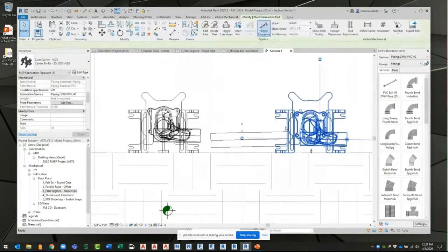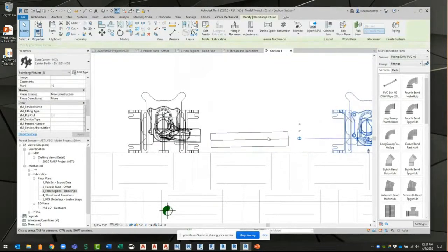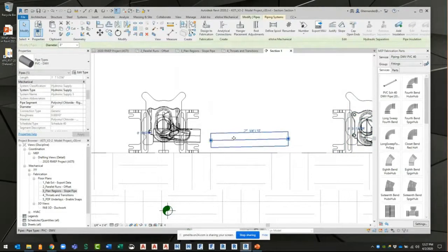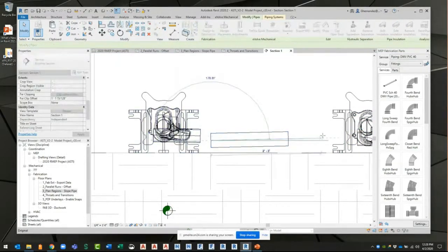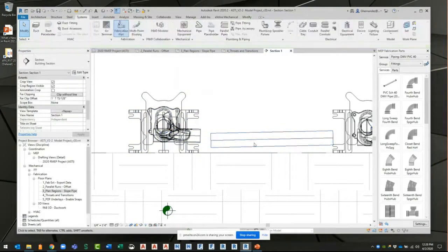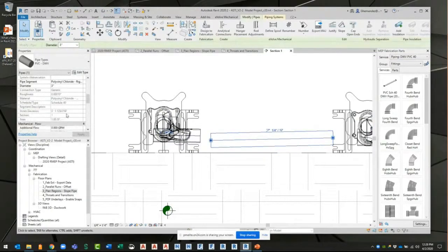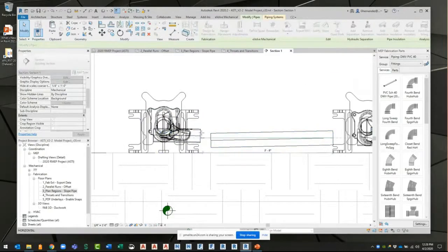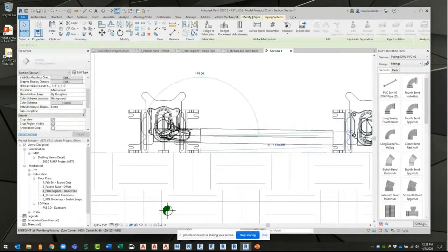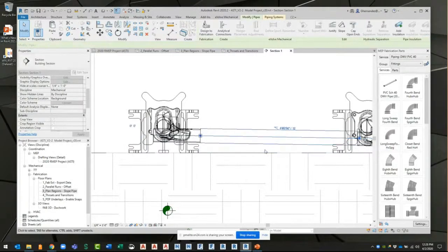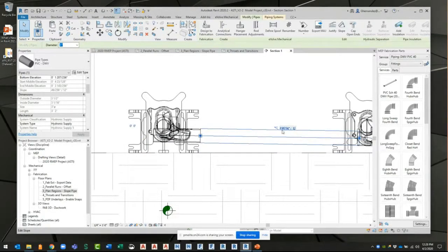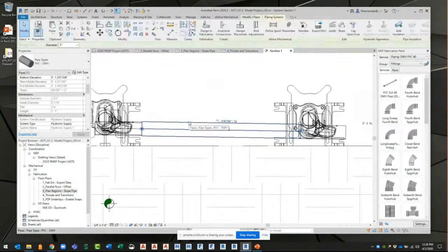So the point that I was trying to show you guys is this here. When you draw in slope pipe, and you drag it like this to extend it or reconnect, maybe I want to drag it from corner to corner, right? If I go into the values over here, into the properties, you'll see that the slope sometimes gets out of whack. And what you would need to do to fix this is, let me move these into play here, see if this even works. See this right here? See why it's got 4 and change over 12 in the slope, right? It won't keep a specific value.